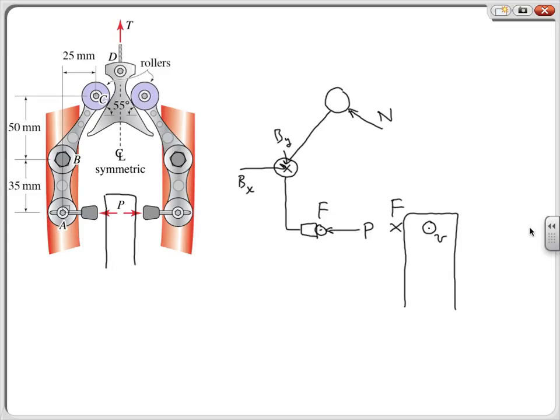So this is also F, corresponding to this X. But then in addition to that, the fact that this arm is trying to be pulled forward is going to require the bolt to sustain a bending moment perpendicular to the axis of its fastener. So we know that the bolted member can allow rotation in the XY plane that we can see here, but it certainly cannot allow rotations out of the plane. So there's going to be a bending moment here this way that's also responsible for this reaction.